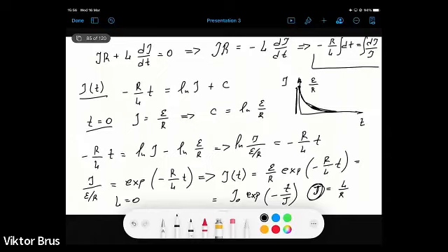We analyzed so-called RL electrical circuits, to be more precise, transient processes, which give us the time dependence of electric current in these circuits in the moment of turning on the circuit, when electric current is increasing over time, and in the moment when we eliminate the electromotive force after reaching the stationary steady state condition and let the current decay in this RL circuit.